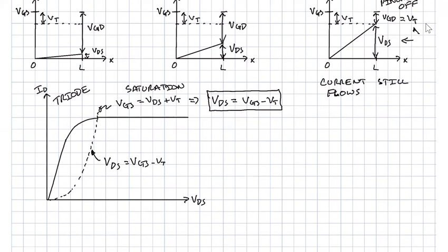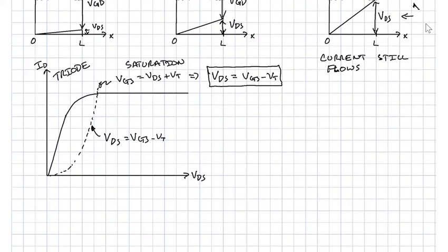Okay, there's one other condition that has to be met here for operation in either region, because we still have, and I'll just make it a little sloppy so we see that there's a line there, but we still have to have VGS greater than VT to have any current flow. If it's less than VT, we're still in that cutoff mode of operation and no current flows. And again, what I said a second ago is true. If you look at the saturation regime, this characteristic looks like an ideal current source.